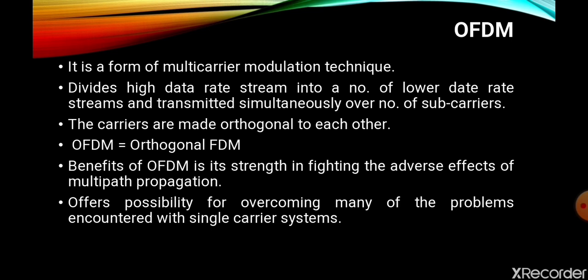Now, the same principle of orthogonality is being applied in OFDM as well. The basic principle of OFDM is to split a high data rate stream into a number of lower data rate streams and then transmit these streams in parallel using several orthogonal subcarriers. That is basically parallel communication.